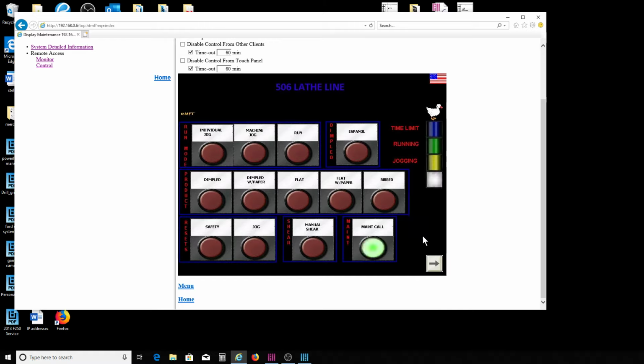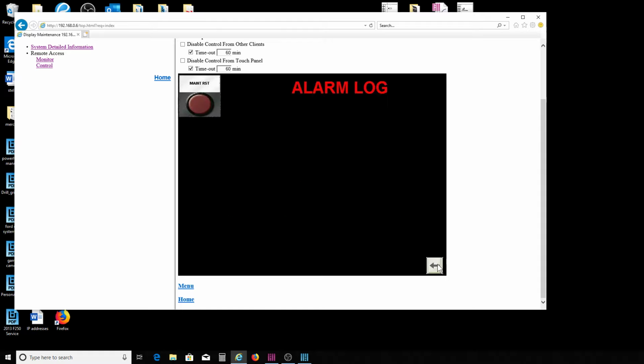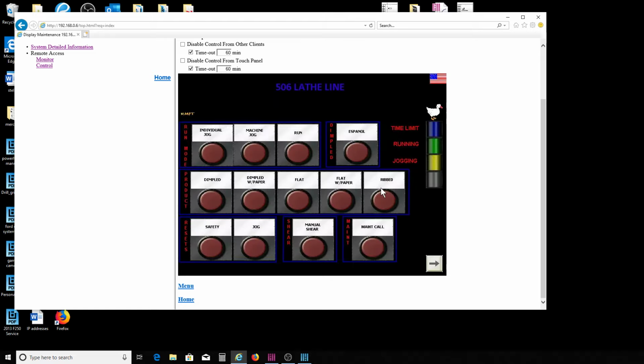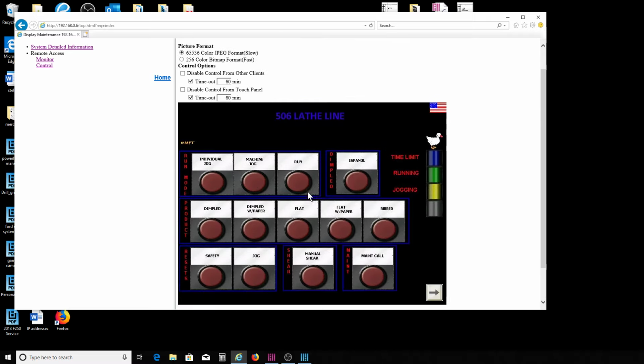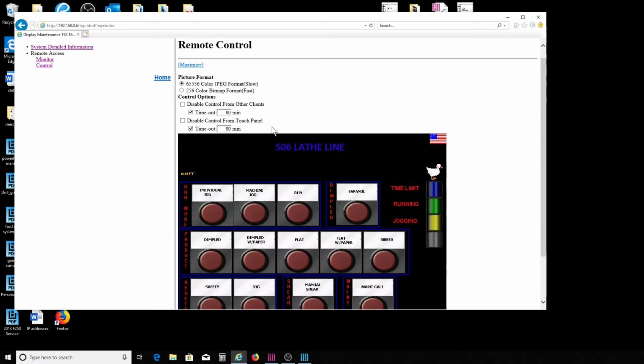See, like I'm going to do a maintenance call. See, now it's making my maintenance light flash on my stack light. Okay, I can go my forward buttons to my other maintenance reset. This is not a fancy PLC program by any means, but it's still under the works. So anyways, you see how you can monitor it all. So hopefully, this to me blows my mind.